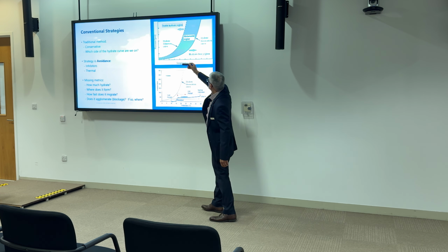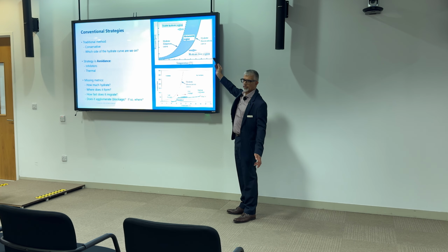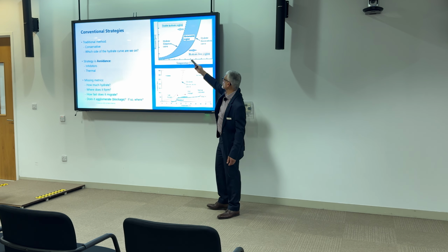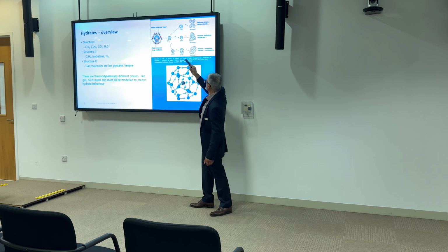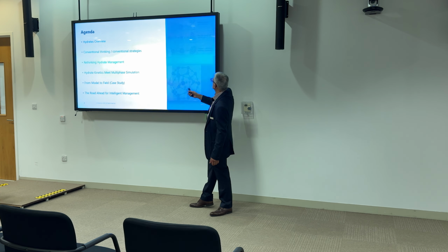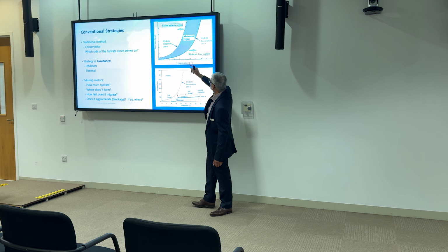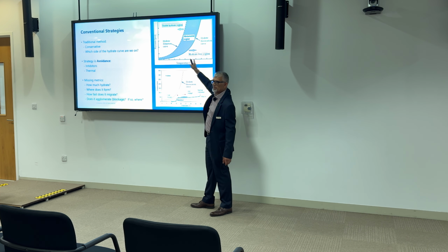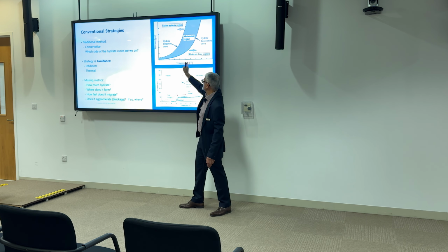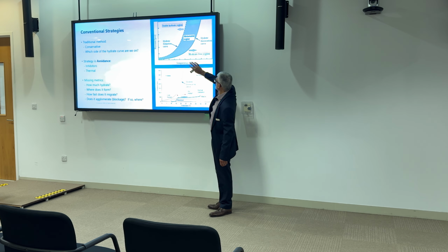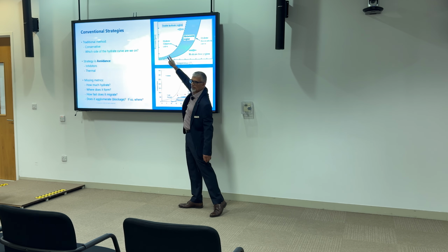So there is a hydrate dissociation curve. Everything to the right, you can't have hydrates forming. You could almost think of it as if this is water: as soon as you go above 0 degrees, ice is going to melt, and as soon as you go below, ice is going to form. So this is very similar behavior. This is the hydrate-free region. Here you get hydrates forming.